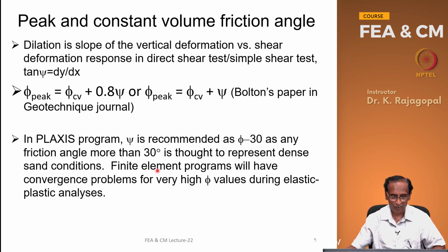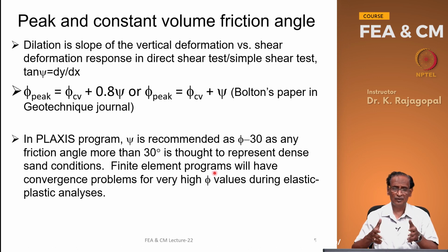And one point that we have to remember is the finite element programs will have a lot of difficulty converging to a solution at very high peak shear strength values. Like if your phi is beyond about 40 degrees, if you try simulating any bearing capacity problem, you will see that the program will just simply fight to converge. You will see a lot of oscillations in the stress that you